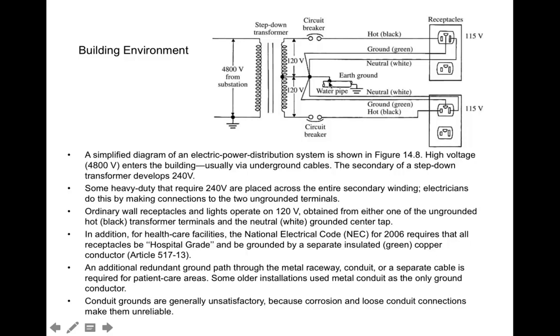In some situations, the earth ground is actually a physical copper pipe driven into the ground. We're not discussing imaging in this particular safety video, but in MRI systems, because those voltages are so high, there is a physical copper rod that is driven into the ground as opposed to trying to ground on the water piping in the building. So that earth ground is formed, and then all of the